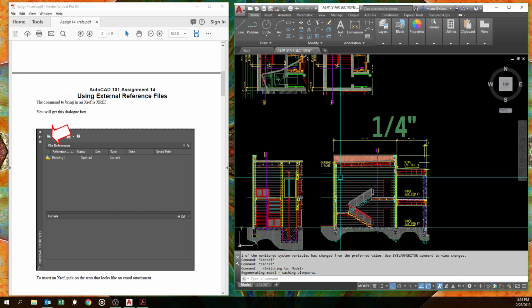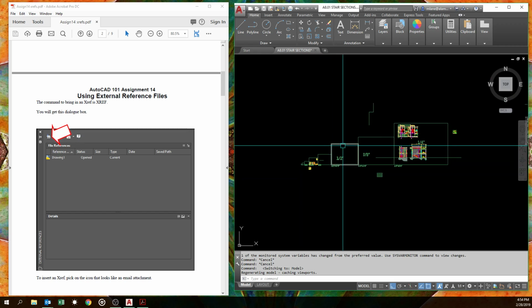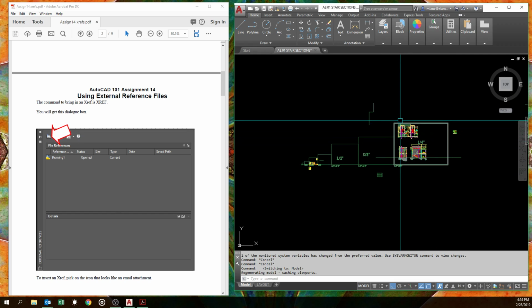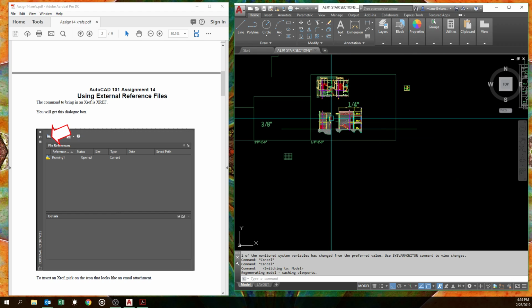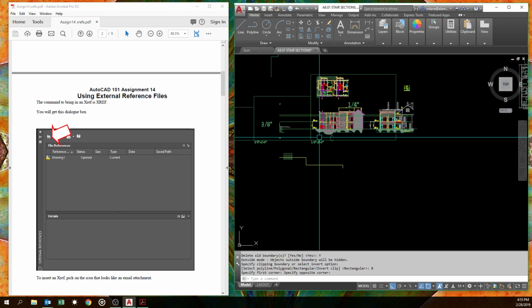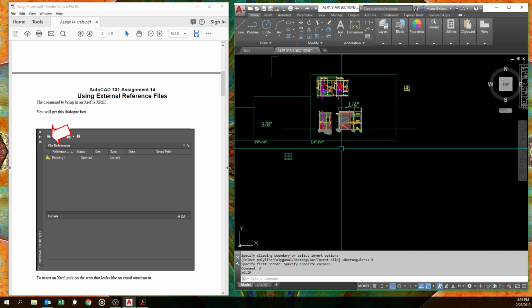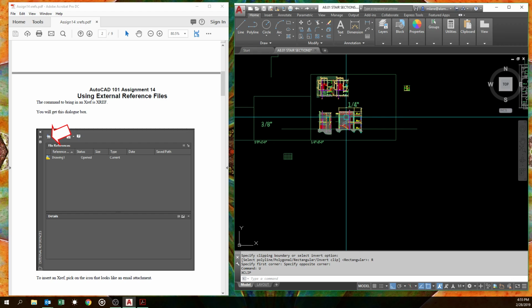These are actually clips from my master file, and you'll notice I've set up my sheet so I've got all the different scales outlined so I have an idea of how big each of the sheets is. But these are Xrefs or XCLIPs from that master building file. If we do XCLIP and I start the whole thing, new boundary, and delete yes, rectangular, you can see there's quite a bit more to it. Don't really want to keep that, so let's get rid of it.